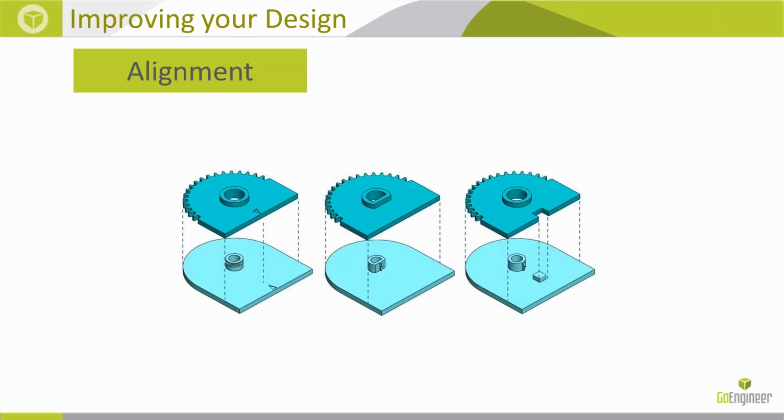We have some built-in SOLIDWORKS design features on the Mold Tools CommandManager. It's called Snap Fit. Mounting bosses are also there. So these aren't features you have to design from scratch. You just have to enter a few parameters and SOLIDWORKS will kind of do the work for you.